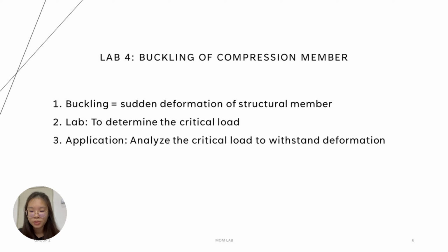After obtaining the results from calculation and laboratory, we will compare them with the graph displayed in our report. Finally, we will classify the compression member for each aluminium strut length using the Euler buckling curve. From there, we can determine whether the strut has no buckling, undergoes inelastic buckling, or even elastic buckling.